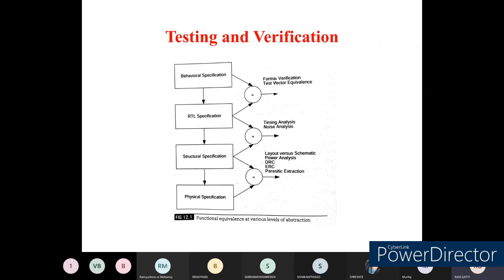After selecting the design architecture, the next step is to divide the given complex circuit into fundamental, individual, independent smaller groups, and for these smaller groups we do the implementation or simulation. The simulation of each subsystem of the entire architecture we call behavioral specifications. So we need to arrive at the behavioral specifications, meaning the input and output relationship, for each subsystem.